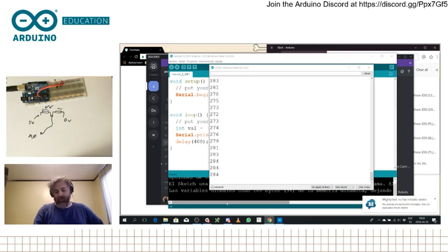And I realized, okay, if a 1K resistor is enough, I don't need to go changing with the other resistors. This means it's probably a 2K as a maximum value resistance sensor, which means that at its maximum value it gives me 2K, and that's kind of like the bridge, the voltage divider I'm making with the resistor, and that's why it gives me the value it gives me. So this works great. You can use this for many things.